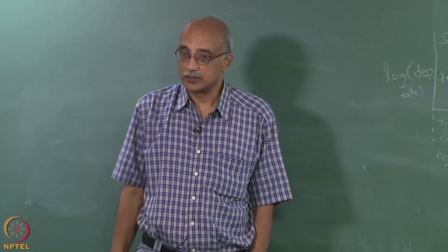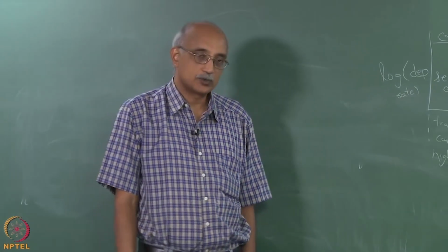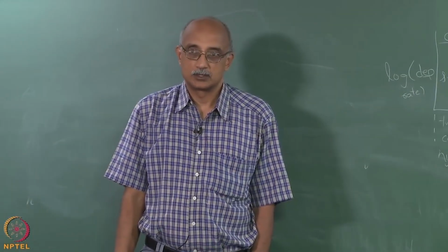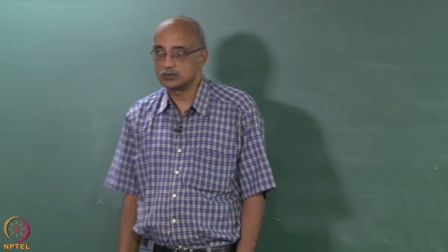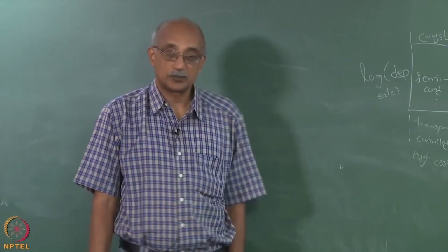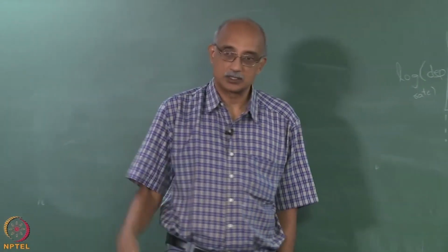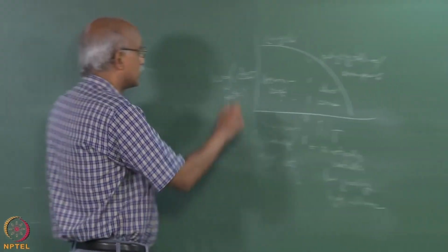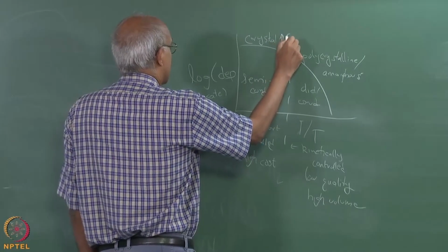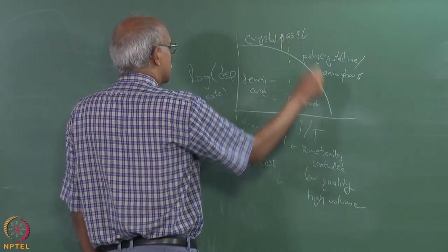It is transport control, right. So, what is the transport property that is affected by pressure? Diffusivity, and as pressure decreases, diffusivity will increase. So, in this particular case, as you lower the pressure, you will actually see an increase in the deposition rate. So, the deposition rate will increase here, but how about here?